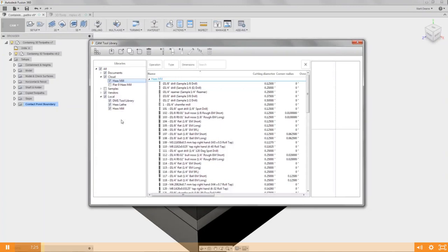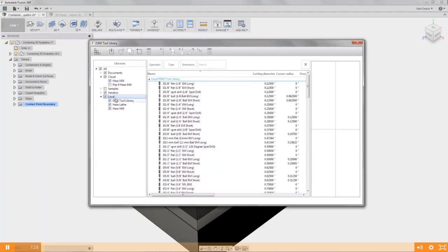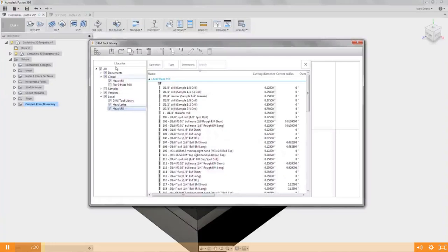So the first thing we're going to look at is library commands, and in here I have 5 commands that are all kind of grouped together. These are library commands. The first one is to import a library. So if I am coming from Inventor HSM or HSM Works, those library file formats are all the same. So I can save out that tool library and just import it into Fusion really quickly and easily. Similarly, we have export, so I can generate a library file from this file,